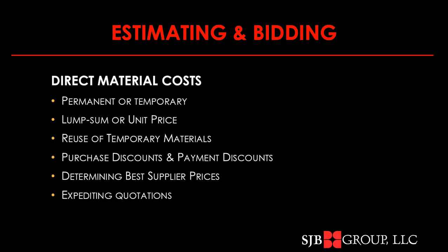To drill down a little bit on determining the best supplier prices. Is the price they've given you responsive? Does it apply to what you really need to meet your contract? In determining the best price, you need to consider, does it meet the required specifications? Is the quote based on exactly the same materials required by the contract documents? Is the supplier able to deliver any shop drawings and submittal materials? Has the vendor acknowledged all addenda for the contract?